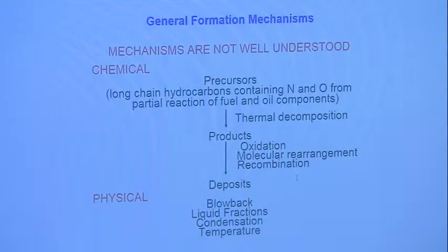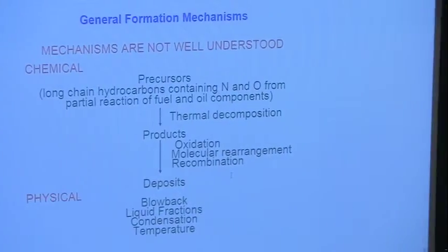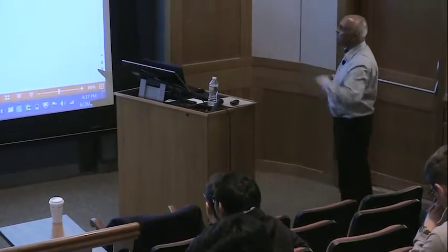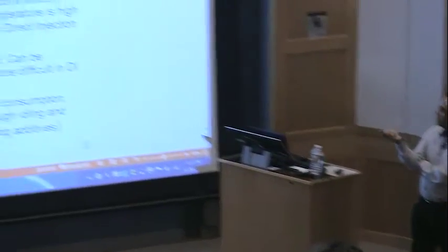There are physical effects also, because things like blowback, liquid fractions, fuel fractions, condensation, surface temperature, all of these are important because they all affect the chemical processes, basically. So both the physical and the chemical processes are important. Now let's look at different deposits, fuel system deposits.